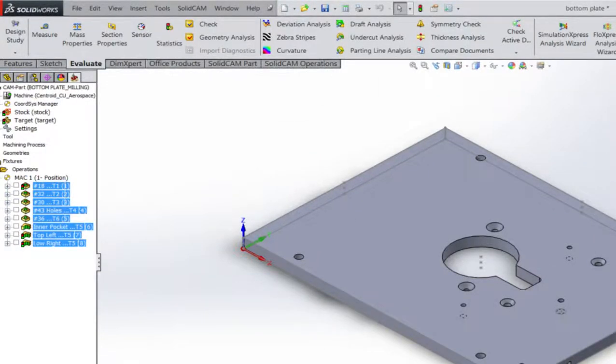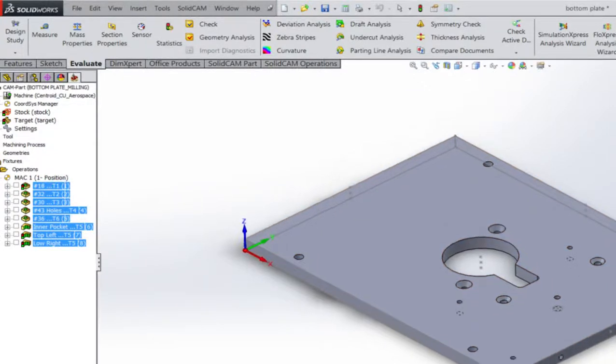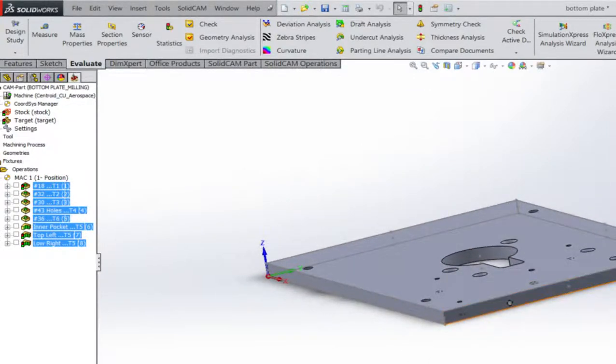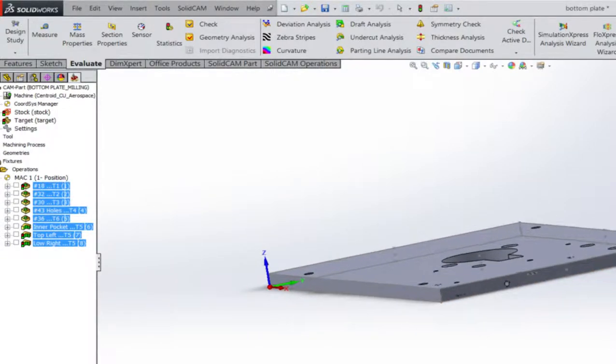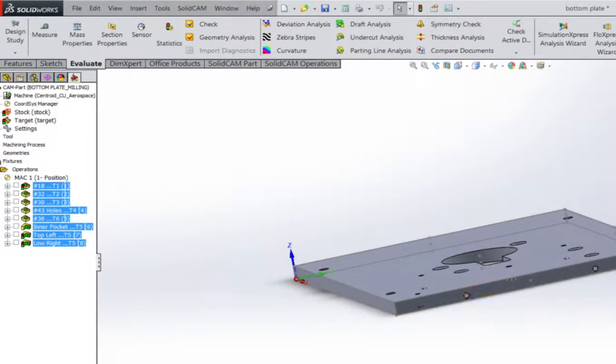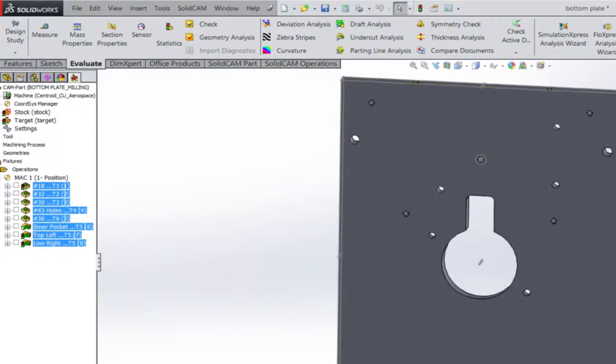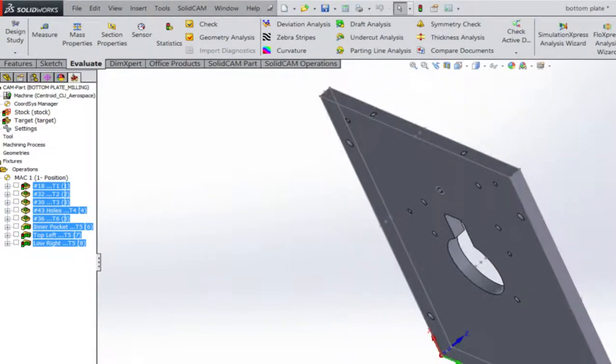Now, I'm going to show you one other thing. You don't have to use the CNCs to drill these last two holes. But let's say you wanted to, okay? More likely what you should do for efficiency in our case is take this plate to the manual milling machine and set it in a vise, clamped up like this, edge find here, edge find here, then you'll have a 0, 0 up here, and then you can drill those holes manually. There's only two of them.